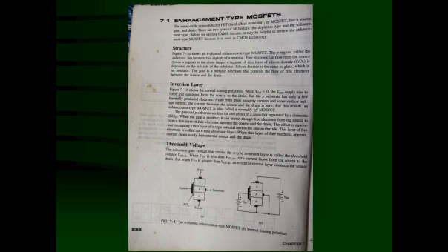The metal oxide semiconductor field effect transistor or MOSFET has source, gate and drain. There are two types of MOSFETs, the depletion type and enhancement type. Before we discuss the CMOS circuit, it may be helpful to review the enhancement type MOSFET because it is used in a CMOS technology. The structure of the enhancement type MOSFET is given in figure 7.1a.